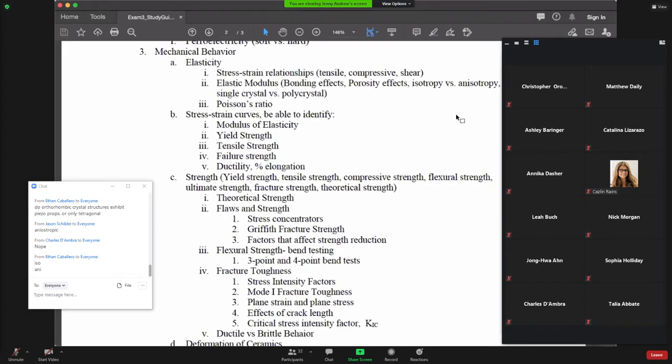One question related to this on the homework: is it possible to decrease the grain diameter from 0.04 to 0.01 through cold working? No, because that would involve compressing a material, and that's not probably going to happen to that extent. Or if you draw it out, you'd be lengthening it in one direction and shrinking it in the other. But yeah, no, it would be a non-uniform structure.